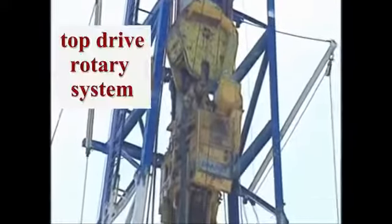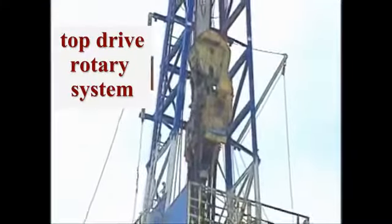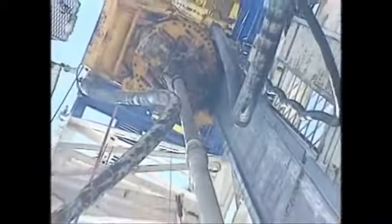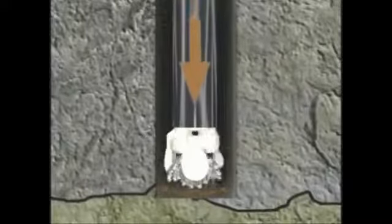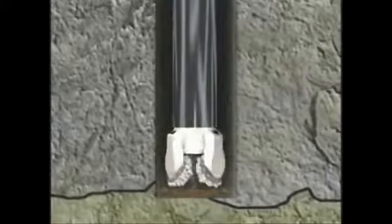Another, newer type of rotating system is called a top drive. The drive shaft, with its powerful hydraulic motor, screws directly into the drill stem. Replacing the Kelly bushing and the rotary table, the top drive suspends and rotates the drill stem. The drilling fluid flows through the top drive, down through the drill stem, to the bit below, just like with the Kelly assembly.